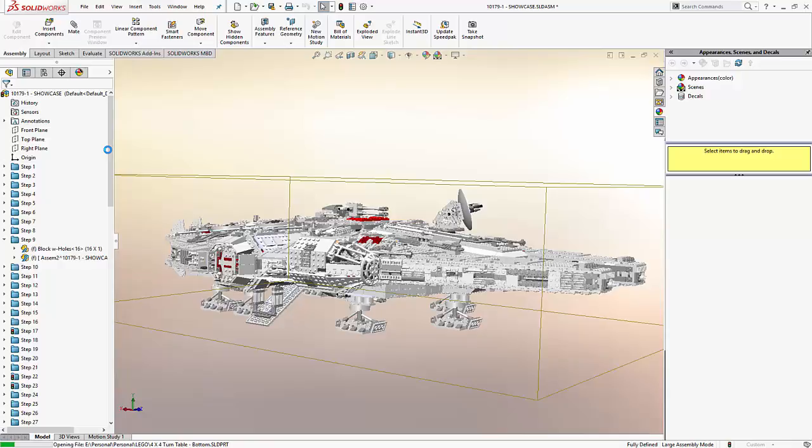Can anybody see the downside of fixing a bunch of components in an assembly? We've got one nut. They're not going to move, right? What if I do an update to a part? What's that going to do to my assembly? It does nothing, right? It doesn't even go to error, because I've got two parts that are fixed in space. So if a hole misaligns because there was a concentric mate on it, well, it's suppressed, so it never goes bad. So that's kind of a big killer.